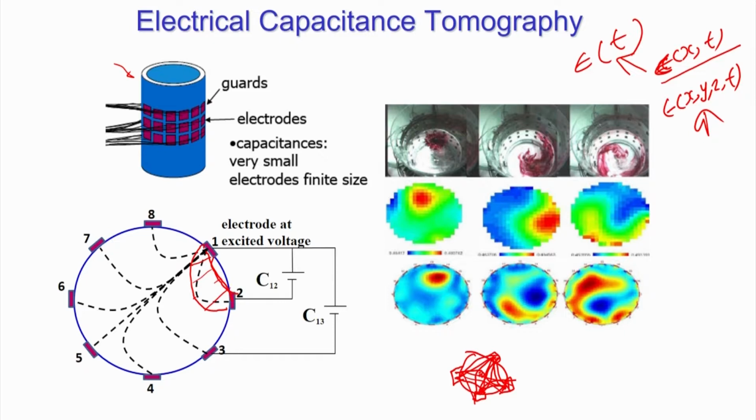So, if you have to measure something which is changing with the time, say in a gas liquid bubble column, if I want to find how the bubble fraction is changing with the time, ECT can be used to find the bubble fraction change within a particular volume or within a region of interest with the time. That easily can be done.